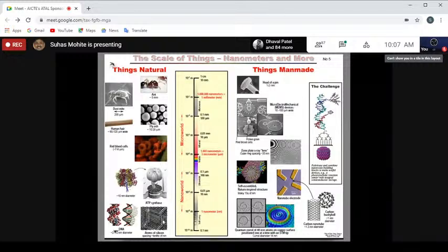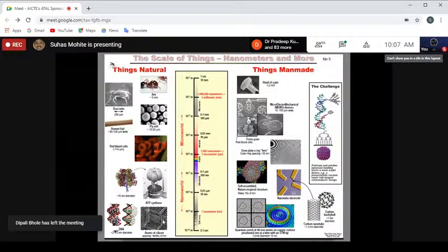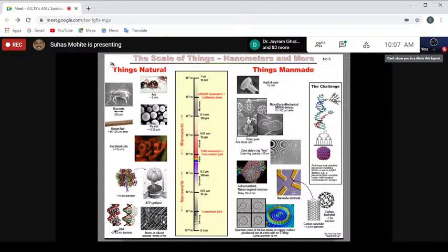For example, if you take air molecules, mechanical engineers are aware of one term called the mean free path of gas molecules or air molecules. It is 70 nanometers. What is the meaning of mean free path? In the kinetic theory of gases, the molecules of gas are continuously in random motion, and they collide with one another, and this average distance of collision is 70 nanometers.